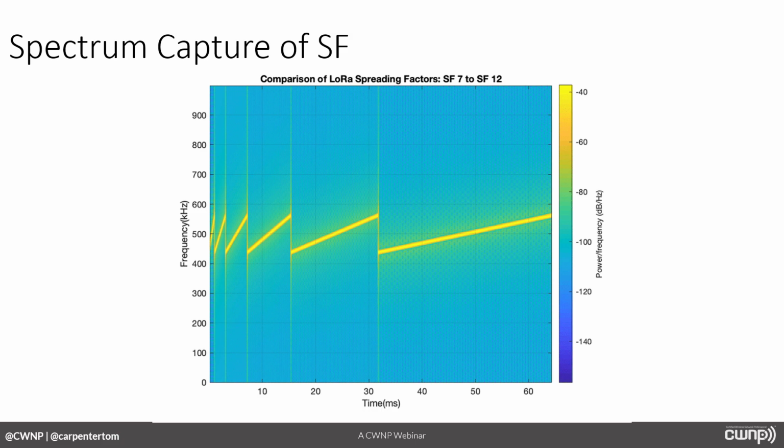Okay, so for example, the preamble, which as you may know from your study of other wireless communications, is the start of the communication, right? The preamble can actually have 8 downward chirps and then 2 upward chirps. And now we'll start talking. So I'm giving that as an example. So we've got downward chirps in sequence and then 2 upward chirps. And now we know, okay, it's time to start the actual data that's being communicated.